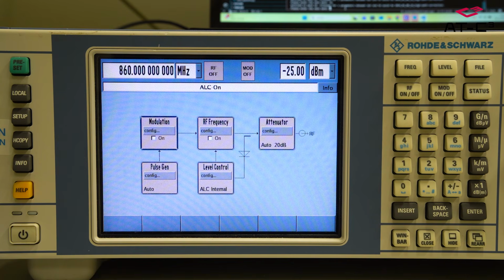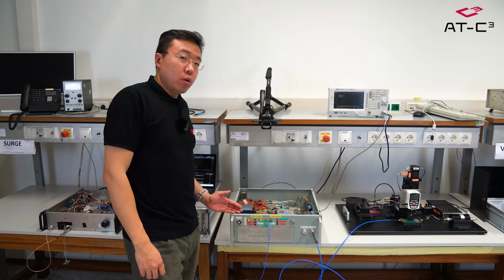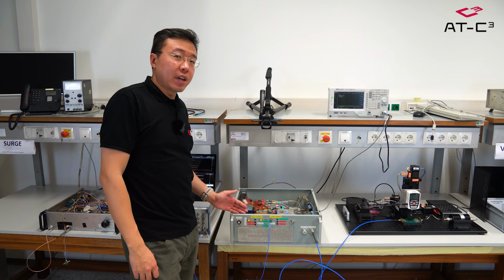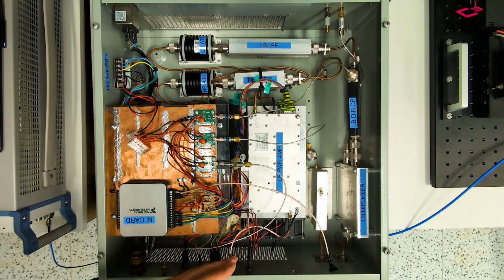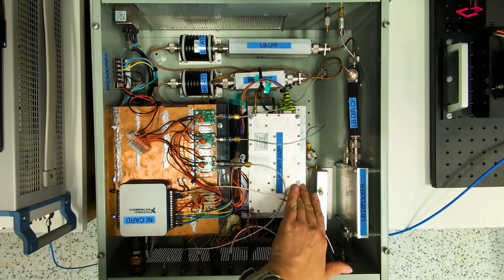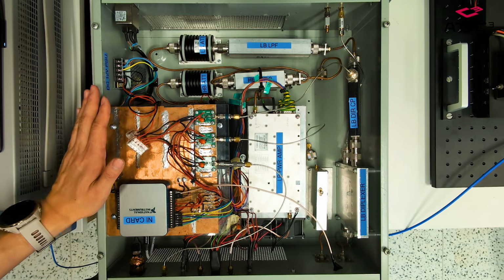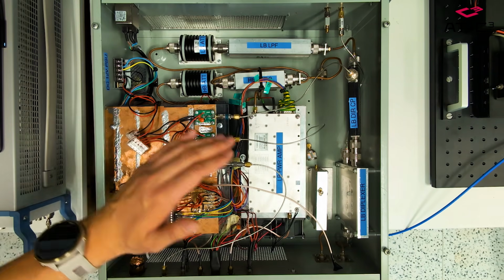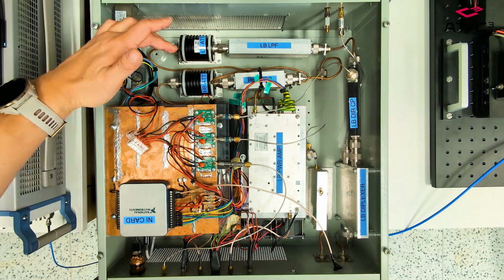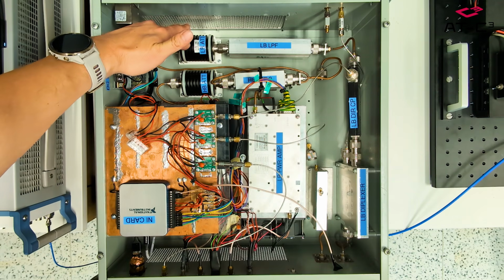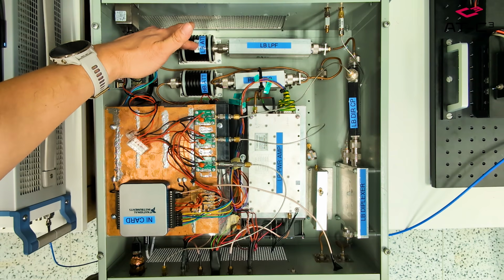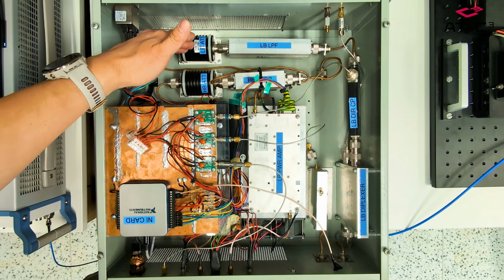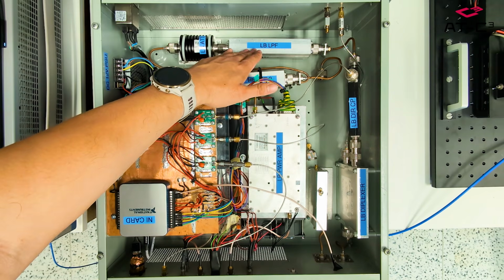First of all, we still need the signal generator to give us the fundamental signal. Then we built our RF module, which includes all the amplification and filtering inside. Once the signal feeds in, it first goes into our power amplifier over here. This power amp can provide around 45 dB of gain. After boosting the signal, the power amp feeds into the 3 dB attenuator. This attenuator is a protection device to prevent an open circuit from causing a strong reflection back to the amplifier and damaging it.